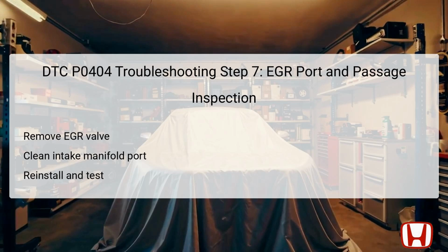Reconnect all electrical connectors and then reinitialize the system. After reinstalling, perform a PCM reset using the HDS, followed by the idle learn procedure. Running the EGR test after cleaning confirms if the passage blockage was causing false P0404 codes or performance issues, restoring proper EGR operation.